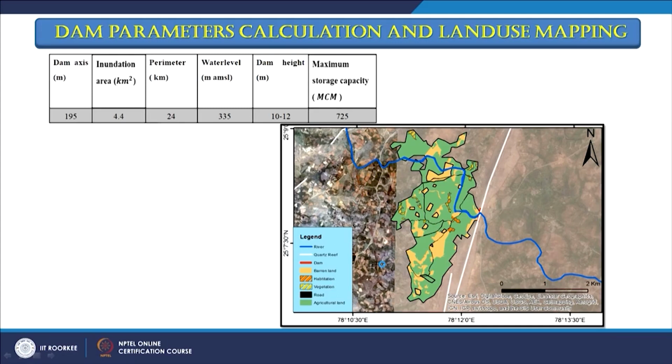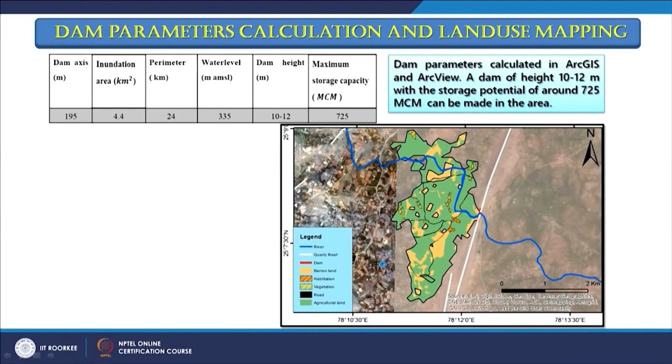Everything is simulated before an appropriate decision is taken. Using satellite images, current land use and land cover can be assessed, as has been done for this case. And if you have revenue records and put in this polygon, the inundated area of the reservoir, immediately you would know whose land will be submerged.